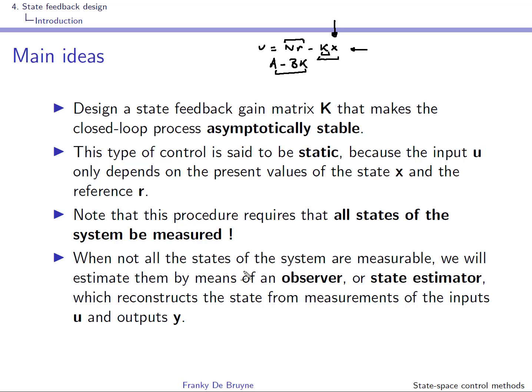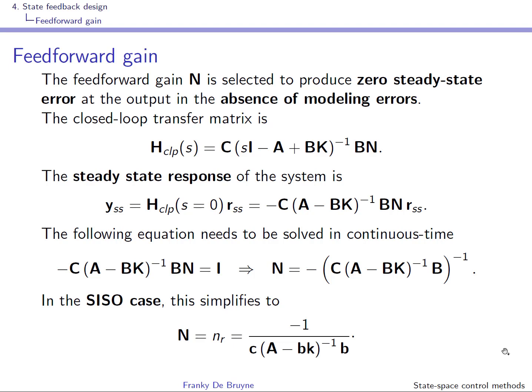And what it will do, it will reconstruct the state that is not measured from the inputs and from the outputs, that are the y's that are measured. Well, in this slide what we do is compute the feed forward gain N, but we suppose that the feedback gain K is already available, and we'll see later in the course how we can obtain it.